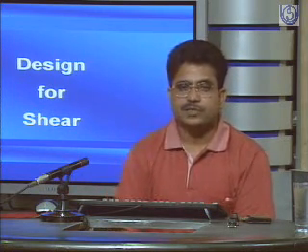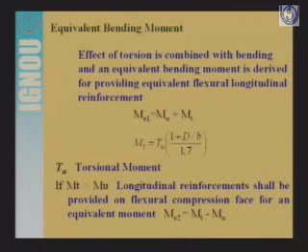So this was about taking care of the torsional moment or torque or twist by adding it to the shear. Second thing is we have to modify our bending moment also if the torsional moment is coming into the picture in a structural member. In this case we will calculate an equivalent bending moment.